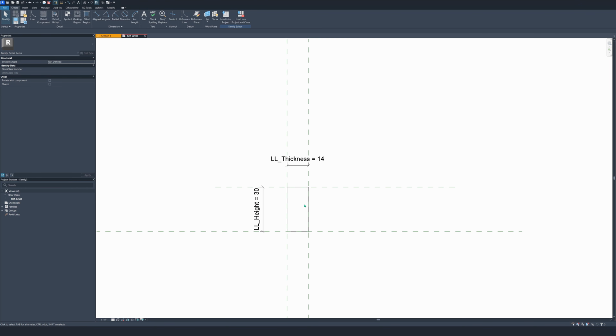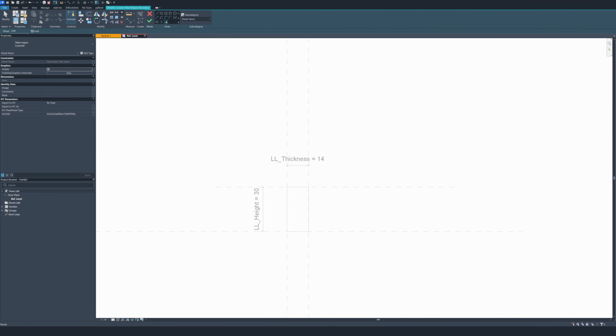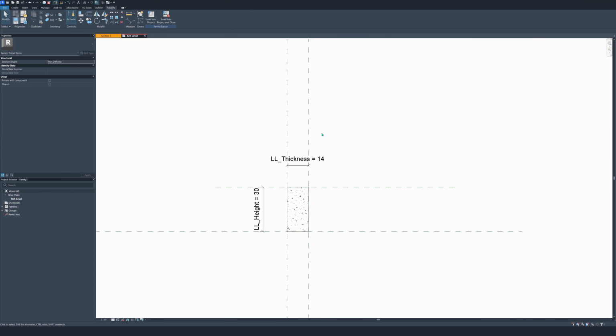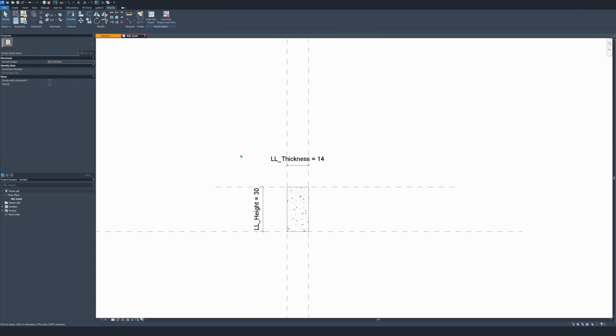filled region on it to have a pattern or not. So right here we go to Filled Region and then you just do Pick Lines again, make sure it's locked, then voila, again the same thing, then trim it as you want, voila, then finish it and let's see if the pattern follows the lines. Again 20 and apply. Yes, it still works. Apply, thickness again 14, voila.